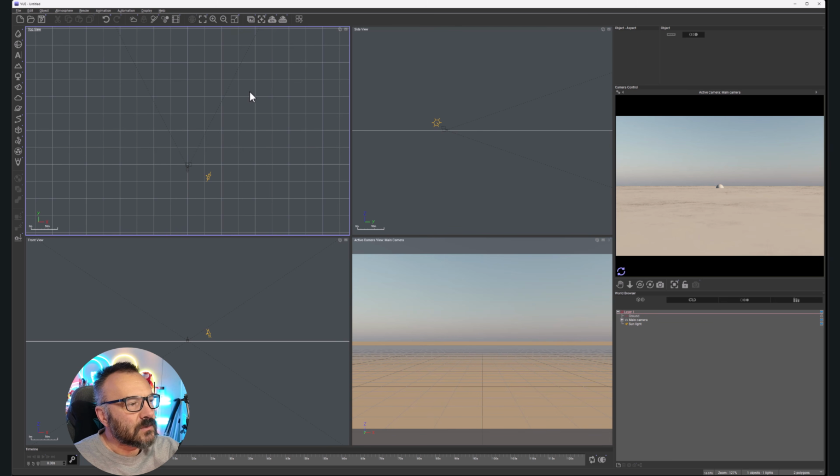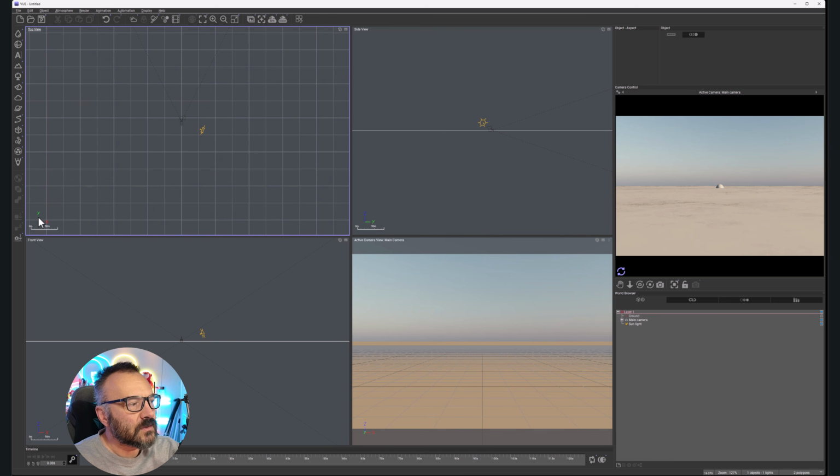Okay, also, as we're looking around here, you'll notice our position X and Y. Just to let you know, the view is a little bit different from Maya, 3D Max, and others, but it's the same as in Carrara, where, for example, X represents horizontal, Z represents away from or towards the camera, so it's on this plane, and Y represents up and down. Many other applications will be opposite: Y will be up and down, X will be horizontal, and Z will be away or towards the camera. So it's a different positioning.